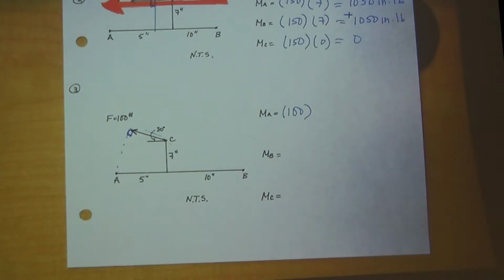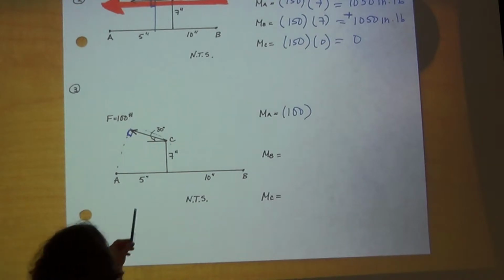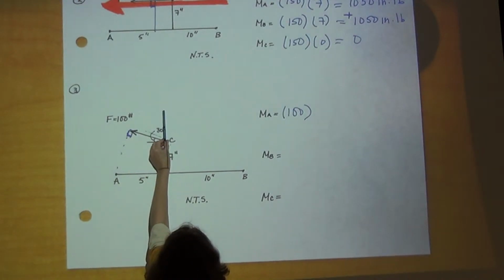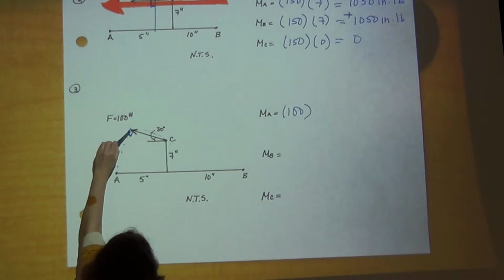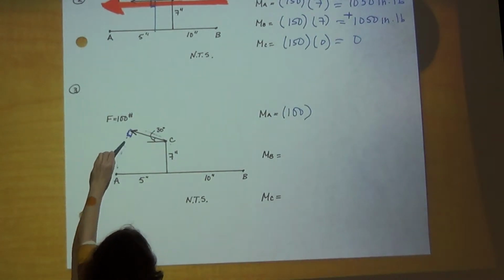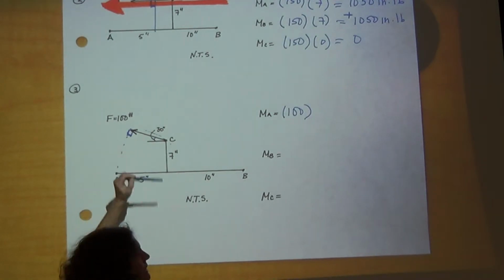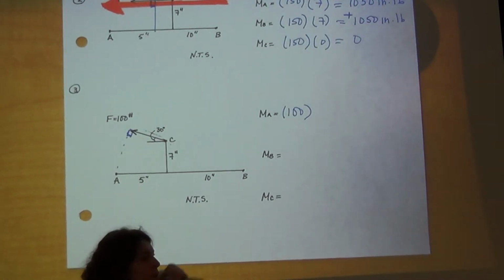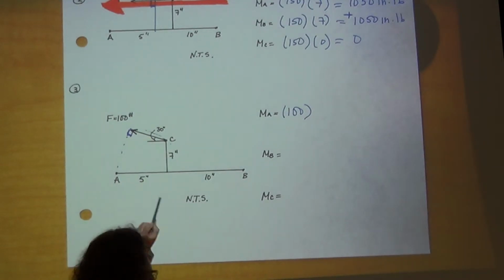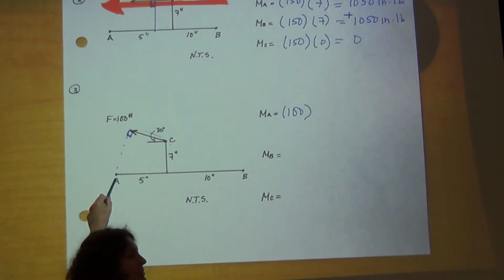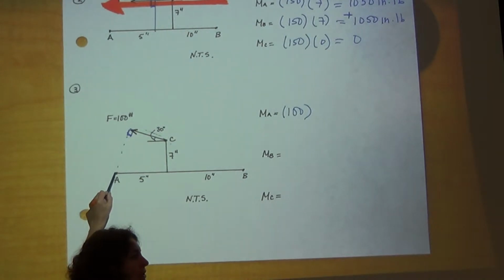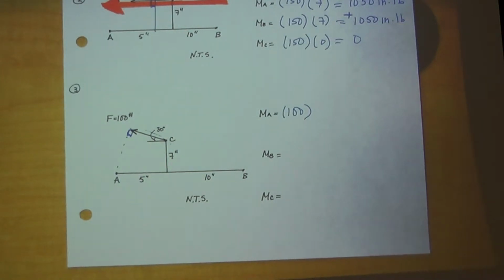I'm trying to set up a vertical axis from point C, and so I will have to rotate downwards to A. Are you still trying, Santiago, to find this distance by using that angle? Yeah. Let's not do that, because it just makes it more complicated. There's something that we can do to the force that we're very comfortable with, where we don't have to find this distance. Jill, do you know what it is? Break it into components. We already know totally how to do that, right?